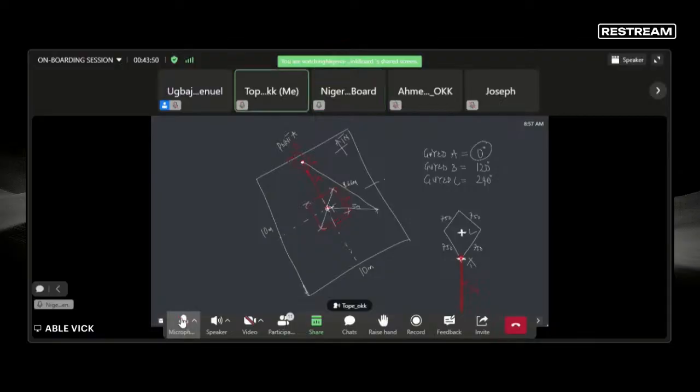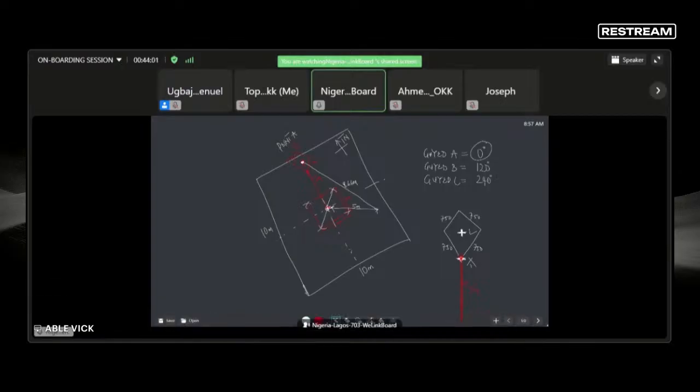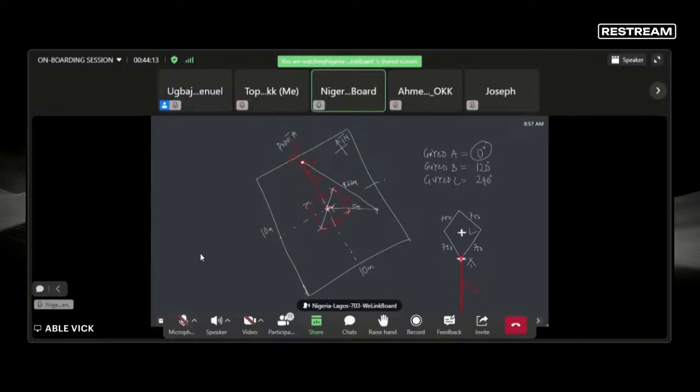You understand it? So you take 8.66 meter. Someone standing at point A takes his tape to 8.66 meter. Whichever direction you want to take it to, no wahala. Someone standing at the middle of tower takes his tape to 5 meter. You now need to make sure, it means someone needs to stand at point B and pull the two tapes together for the two tapes to meet at 8.66 and 5 meter.